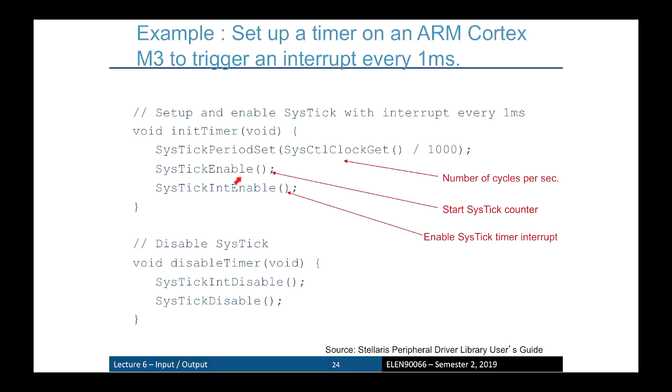So there are functions that allow a little system timer to be enabled, and also you can run this function in order to make it generate an interrupt. So in C, a lot of that's hidden from you, right? You get given these nice functions to be able to turn things on and off, turn the interrupts on, turn the interrupts off, enable, disable. So that's all I need to say there.